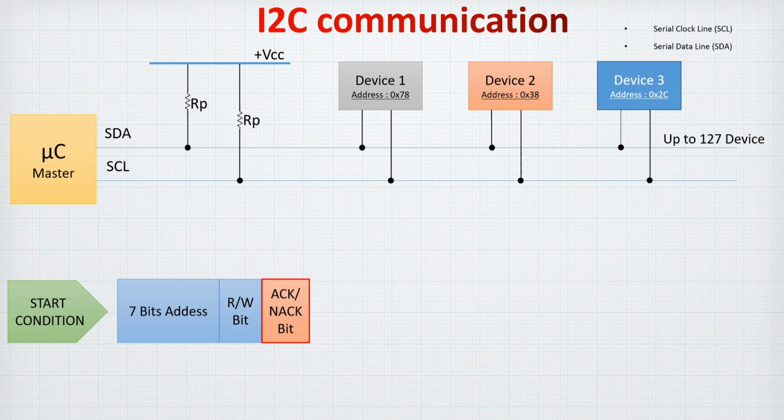And finally, the slave devices will send back an acknowledge bit or not acknowledge. If there is no acknowledge, there will not be anything, but an acknowledge means that the device has understood that there is a signal. And this is to establish the communication with the slave, and will initiate or activate the slave that we are going to select.